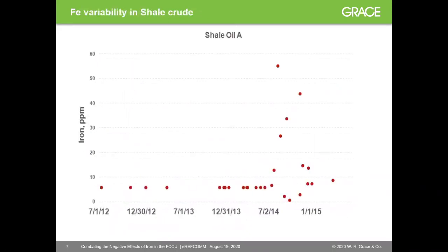While iron can be present in many crudes, it can be found to be especially common in tight oil-derived feeds. The PES protocol had been set up to sample all incoming crudes, and in the limited time that PES had been testing crude sources, it became apparent that iron could be variable within a specific crude. Large iron spikes can have significant consequences.